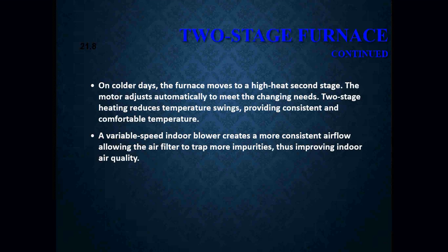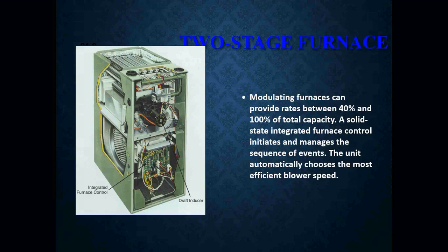The 2-stage heating reduces temperature swings, providing consistent and comfortable temperatures. A variable speed indoor blower creates a more consistent airflow, allowing the air filter to trap more impurities, therefore improving your indoor air quality. Here is an example of a 2-stage modulating furnace.